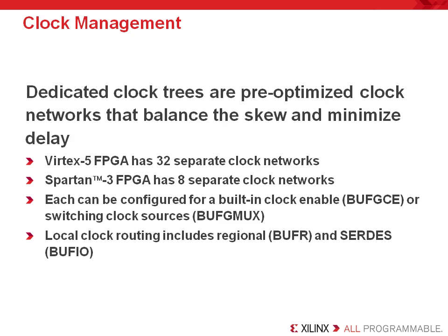Clock management resources include a series of dedicated clock trees, which are pre-optimized clock networks that balance the skew and minimize clock delay. In Virtex 5, there are 32 separate clock networks. In Spartan 3, there are 8 separate clock networks.